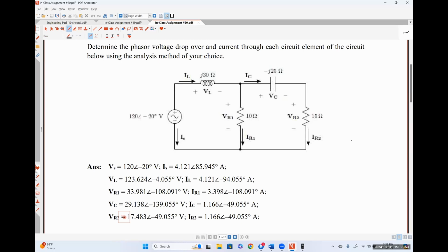So again, I'm not trying to overwhelm you guys, but looking at this circuit as if it were just a DC circuit. So treat all of those inductors and capacitors just like they were resistors. What might you do to solve for, let's say, any of those voltages?